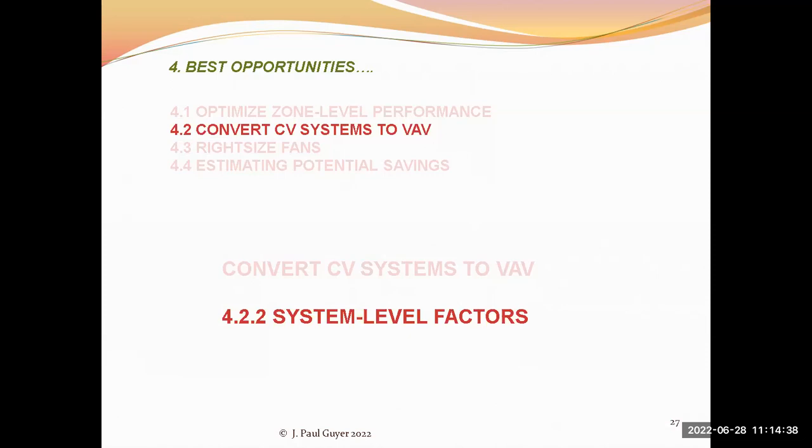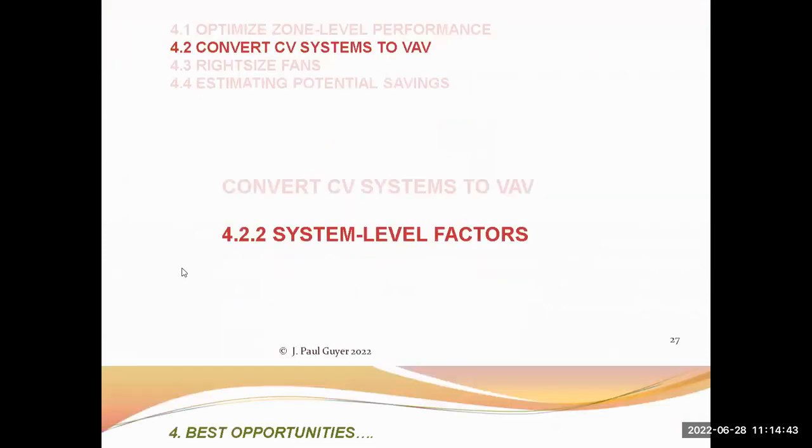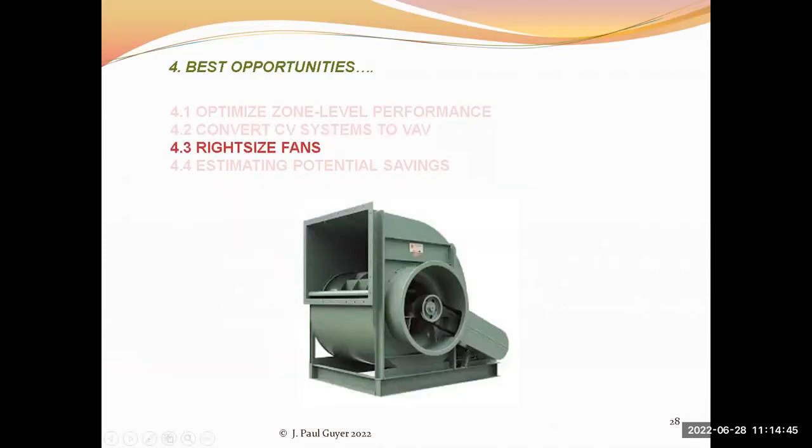Now, the next opportunity that is frequently a good cost-effective one is to right size the fan. The fan in the older building may well be too big for the load that it is currently serving. And this can be due to things like I pointed to earlier.